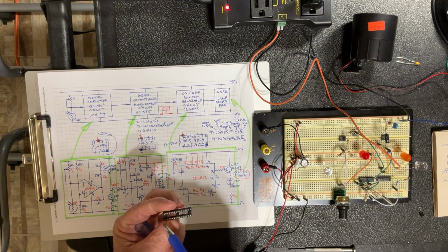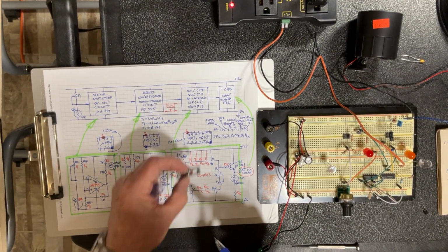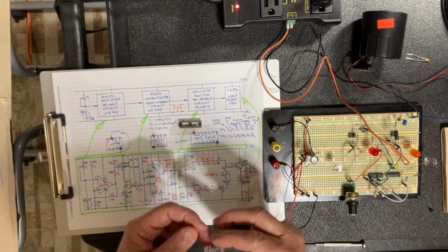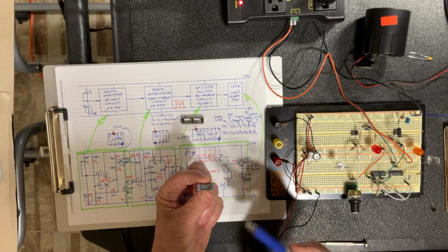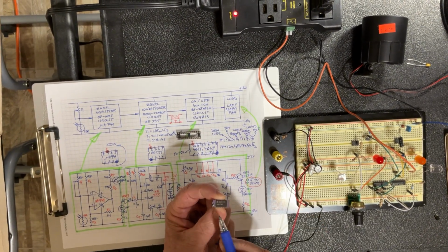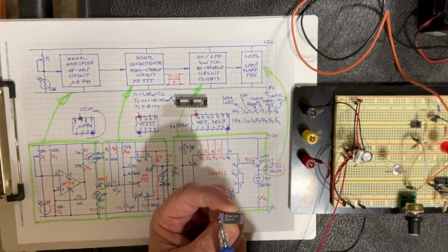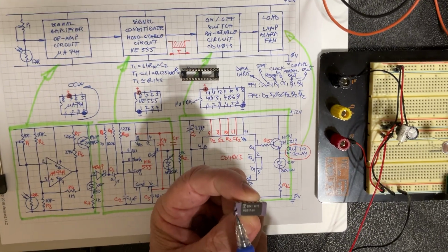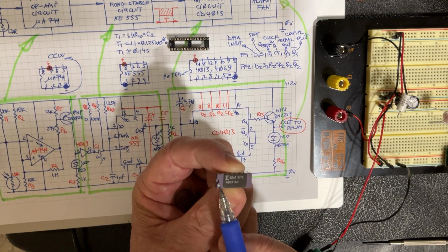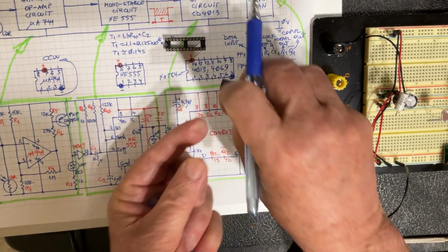This is why, even on the socket you place these packages on, you have the notch. And if I take a look at this little package, I can see not only the notch, which is over here, but some manufacturers also put a dot. It doesn't matter the color; in this situation it's white, it can be black. The dot is right above pin number 1, because its purpose is to identify where pin 1 is, to start counting counterclockwise.